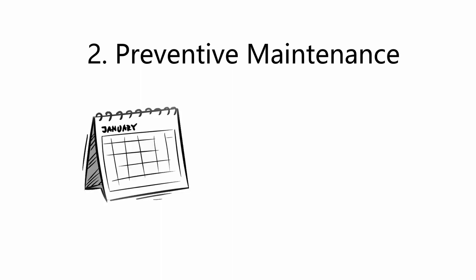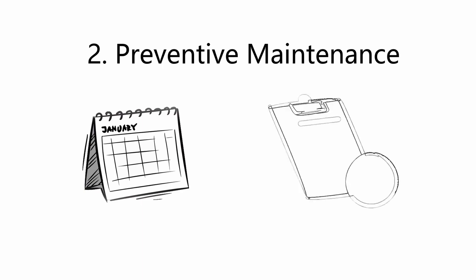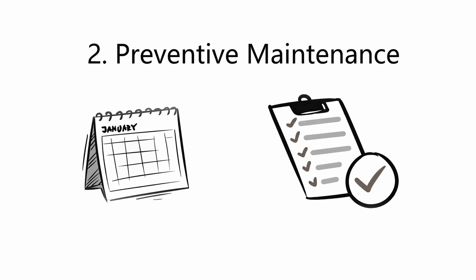2. Preventive maintenance. Maintenance carried out at predetermined intervals or according to prescribed criteria, aimed at reducing the failure risk or performance degradation of the equipment. The maintenance cycles are planned according to the need to take the device out of service. The incidence of operating faults is reduced. 3. Risk-based maintenance.